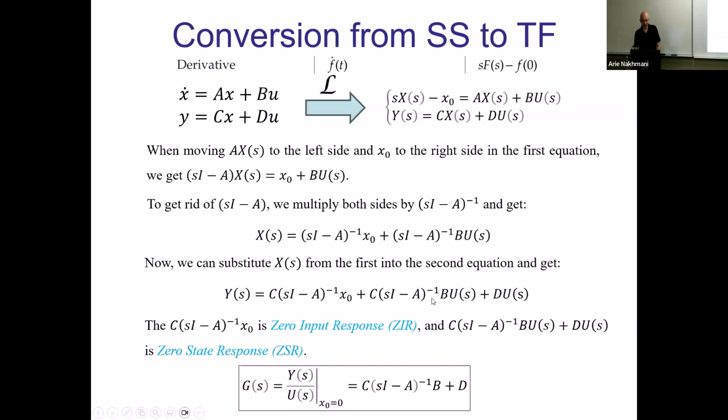What is left? That part and that part. Any questions on the transfer function and how you get there? You're just using that formula. Done. It's that simple. You're just taking matrices A, B, C, D, putting them into that formula, and you find a transfer function. This will be a rational function here, if you compute all of the things. Questions?